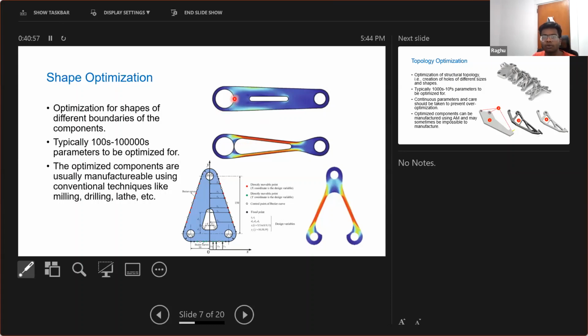Say the torque with which you want to rotate, say the maximum stress you are expecting on this wrench is some 50 megapascal. For 50 megapascal, this solution would work great, and you should make sure that you would not use this wrench for applications where there would be more stresses than 50 megapascal. Then it would break, right? Because you didn't inform the optimizer that you are going to force stresses of more than 50 megapascal.